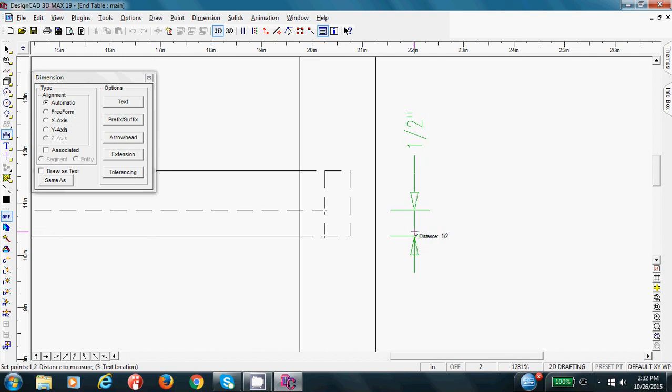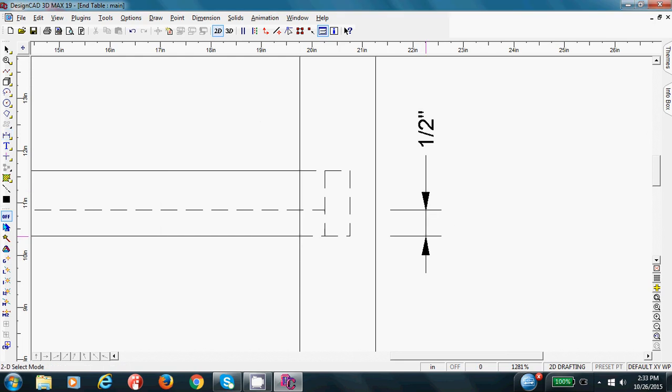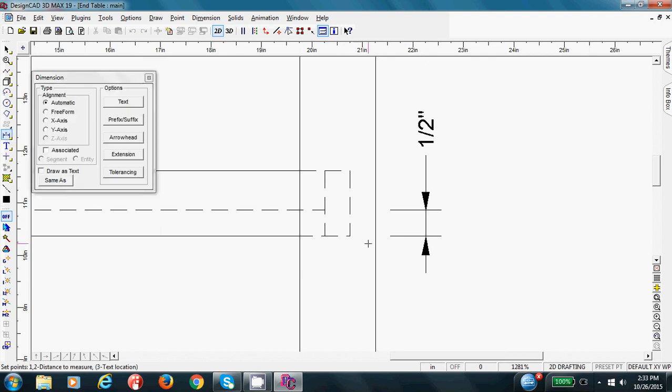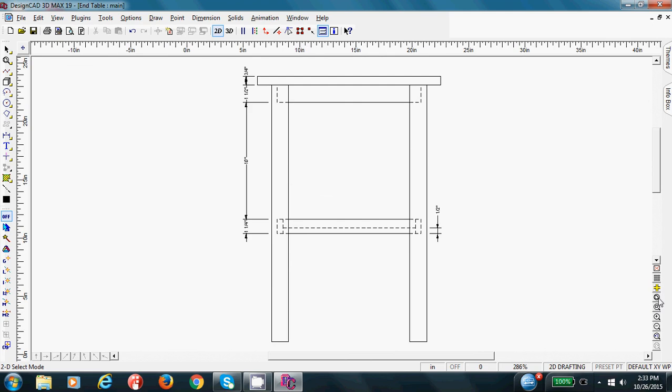And I want to go point relative. I want to be 1 inch past this outermost line. So to go 1 inch past, I have to add 1 inch, 1/2 inch, and 1/2 inch. So let's try that. Point relative, 2 inches to the right. See what that looks like. Okay, I think that looks good. I can do a rough measurement with this tool. From here, just a rough measurement. This should be about 1, and it is good. Fit to window. And there you have it.